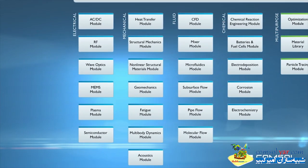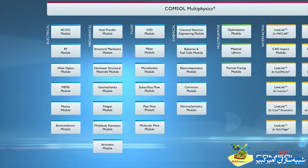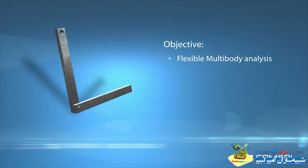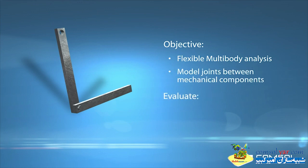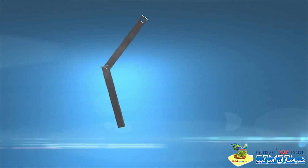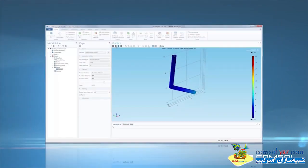This video will demonstrate the modeling of a double pendulum using the Multibody Dynamics module, available for use with the Structural Mechanics module. The primary aim of this model is to perform a flexible multibody analysis. Here we demonstrate various features available in the Multibody Dynamics module to model joints between mechanical components, such as joint forces and motion tracking. We will perform a transient analysis of the double pendulum motion and track the locus of the bottom tip of the double pendulum as it oscillates under gravity load.